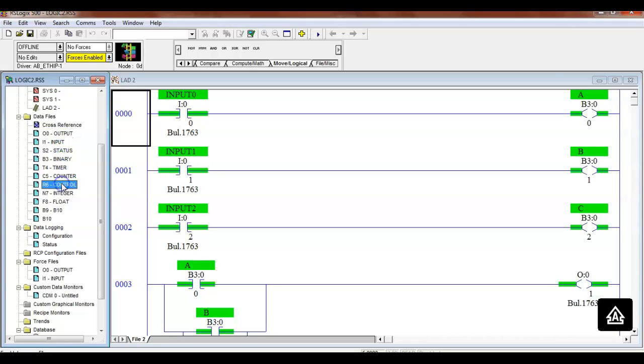You won't find the term register in the Allen Bradley manual. Usually a register is inside the microprocessor. These are not inside the microprocessor. Anybody had anything to do with that? But the guy in the book calls these registers. These are not registers. These are data files. So on the test, since the book calls them registers, I'll put it in parentheses, but out beside them I'll put data files. We can't access the registers inside our processor.